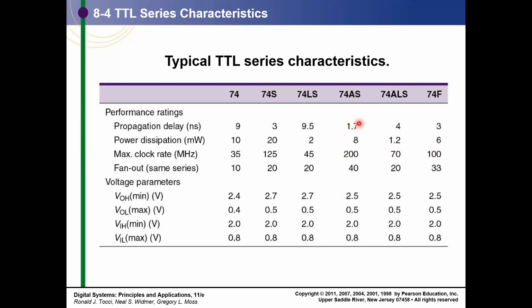Directly comes from your propagation delay. Okay, it is twice, almost twice. So you see half, almost half. Fan out: how many devices you can connect on the output, or how many more gates can be driven or connected on the output of a particular series. See, to begin with, it was only 10 max.